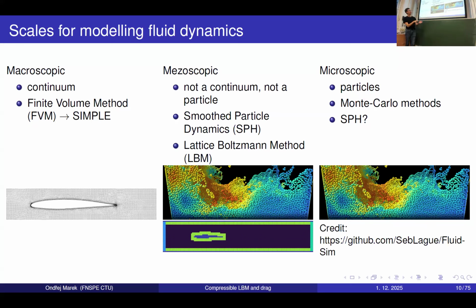Here is smoothed particle dynamics, which takes particles, imagine they are just a reduced version of the physical particles, and their collisions are also smoothened out, so that there is no randomness in the collisions. Sometimes SPH is called mesoscopic or microscopic, but in between the microscopic and the macroscopic is the mesoscopic, where we represent not the particles, but also not just the continuum, something more.